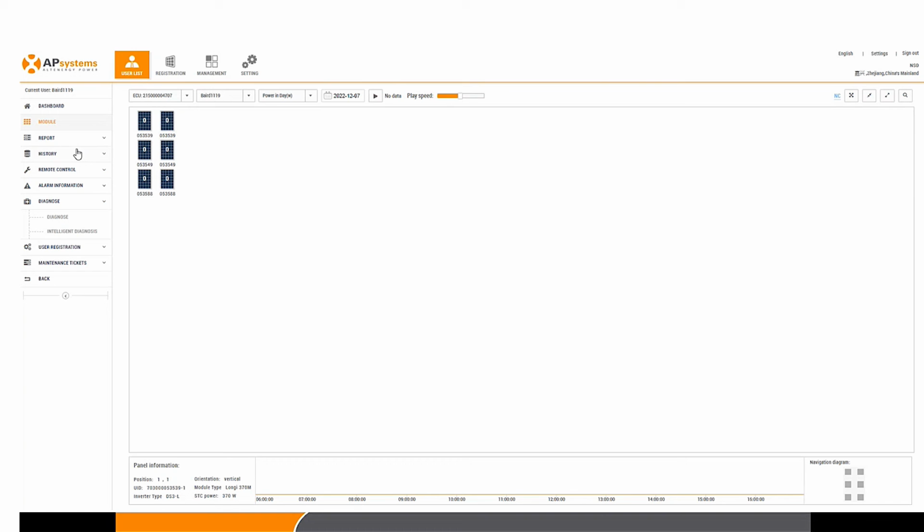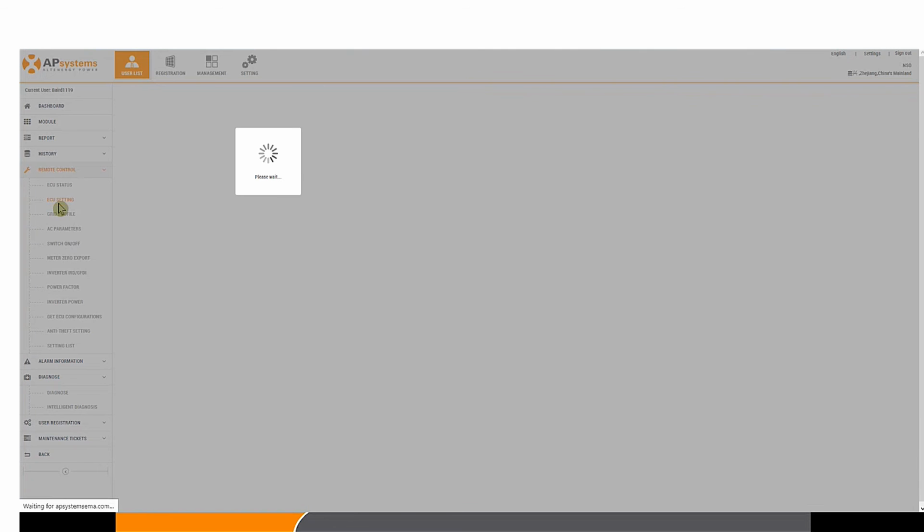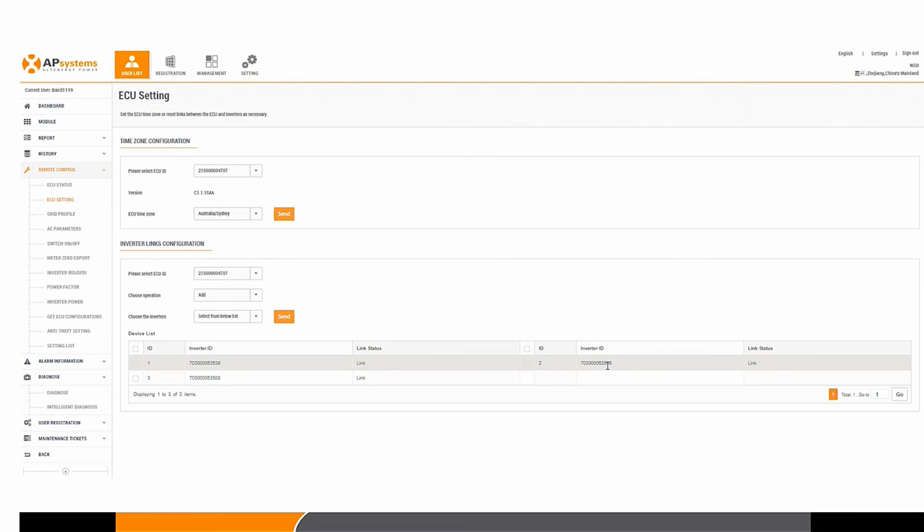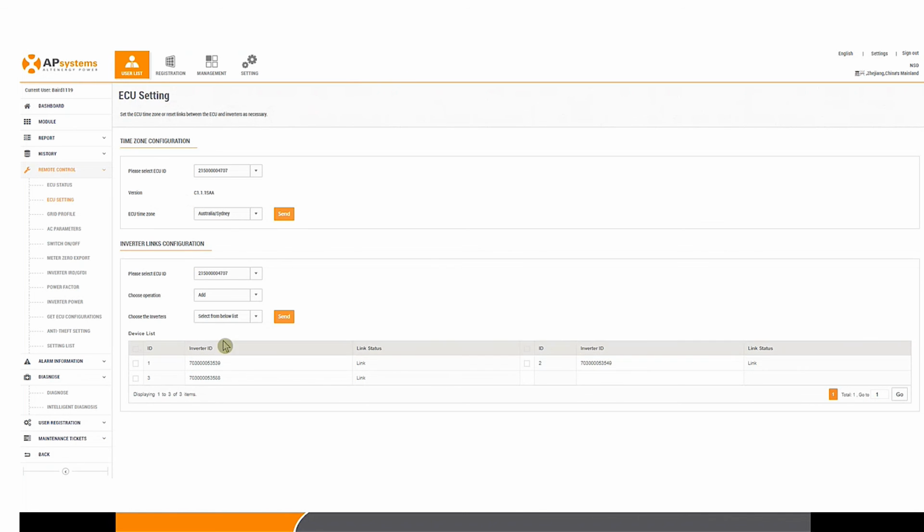So the steps you normally want to do is make sure 2 things. First thing you want to check is the panels linked? Yep, it's linked. And the second thing is you want to check the version. Okay, now this is something that goes with experience, but for ECU, this is 215. That's ECU C. Any version less than 1.2, the DS3s will not link.